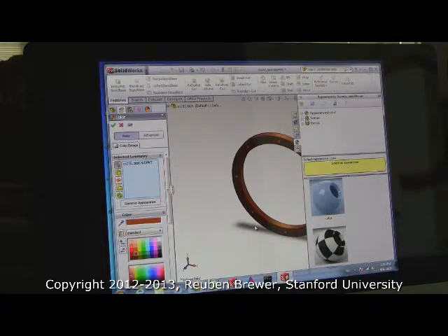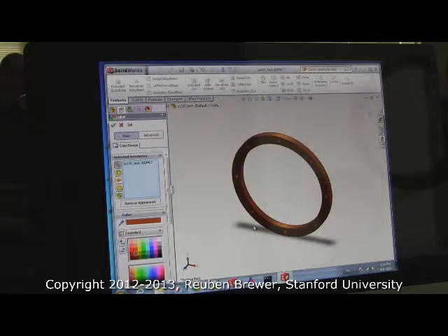Okay, so some of these holes are precise, some aren't. The 3.2 millimeter ones are meant to be through holes for screws. That is, the screw goes through it, it has clearance, but that's all it does. And some of these are for dowel pins. The 2.6 millimeters are press fit for dowel pins. So it's good to color code things so you know what's precise and you have to pay attention to and what's not. For these four little holes, I want to turn them blue.